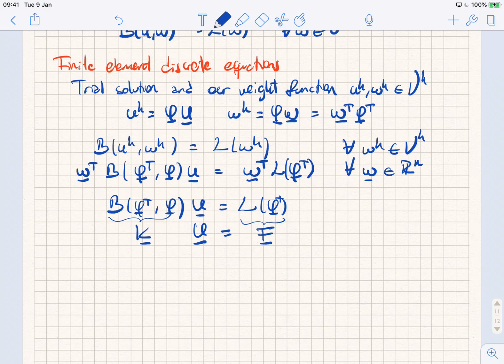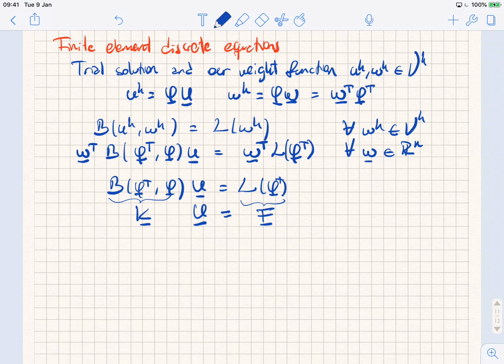Yeah. So when we write u_h in terms of phi and capital U, U is a matrix, right? U is a vector. But u_h is also a vector? No. u_h is a scalar field, but what you have here is the product of two vectors. It's a scalar product. It's just that in finite element terminology, normally you see it written like this.